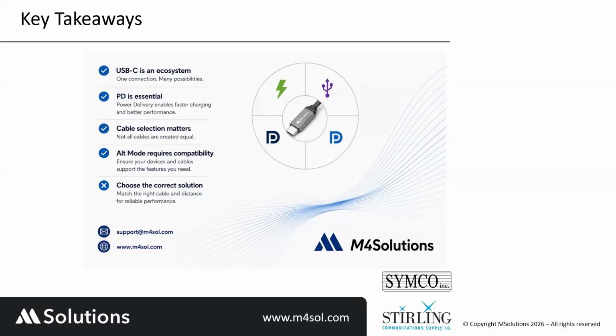Power delivery is essential for the modern BYOD and the meeting room installation. Without proper PD negotiation of the USB-C, many systems will not operate as expected. We're seeing that on integrations that are failing due to those power delivery requirements. Cable selection matters. It's a very important part. Choosing the wrong cable is one of the most common causes for installation and interoperability issues.